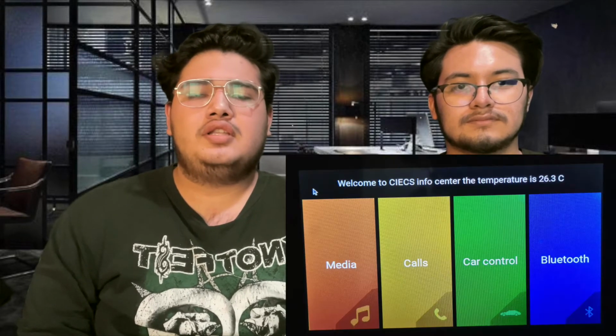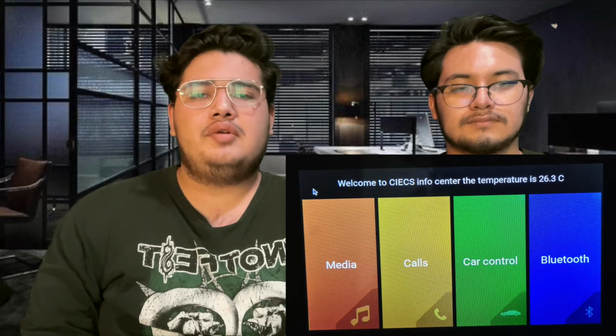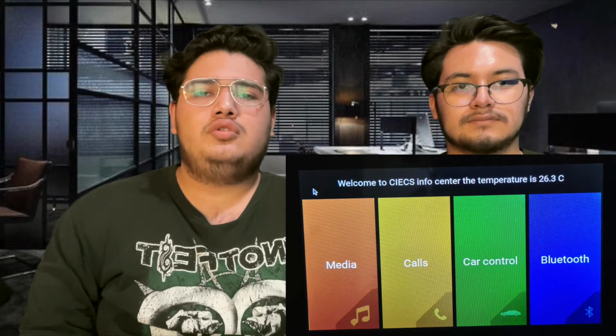Reaching this point, we wanted to see if we could bring together the graphic control and the hardware control. So we implemented code that shows us in the interface the ambient temperature using the DHT11 sensor and its own library, and the general purpose input-output library.